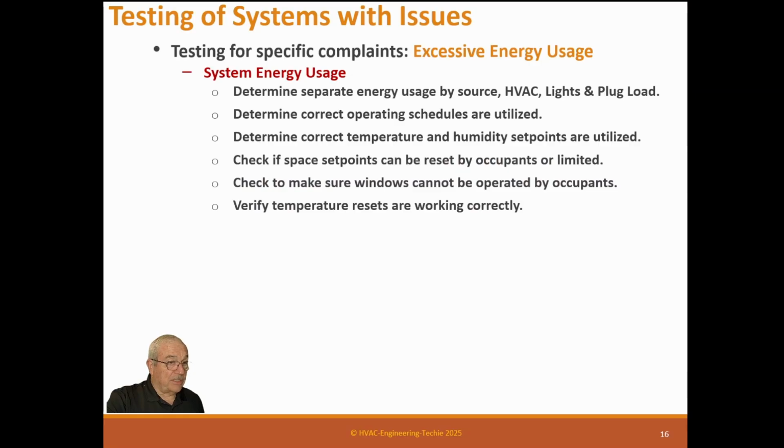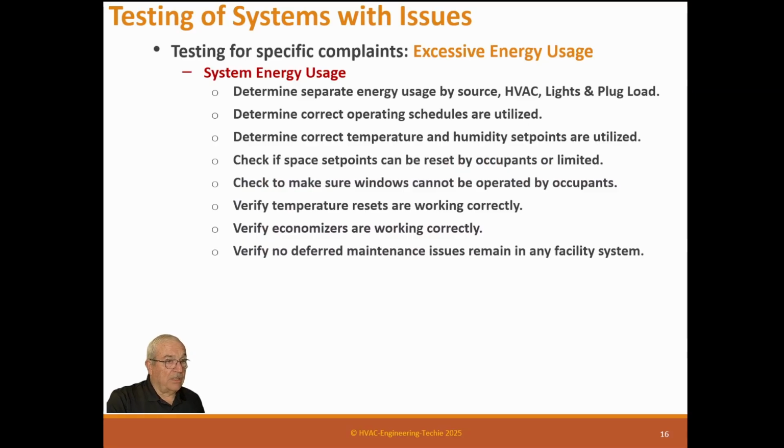Remember, temperature resets and humidity resets, all resets are key to energy efficiency. Verify economizers are working correctly. Verify no deferred maintenance issues remain in any facility system. Deferred maintenance is not an option.